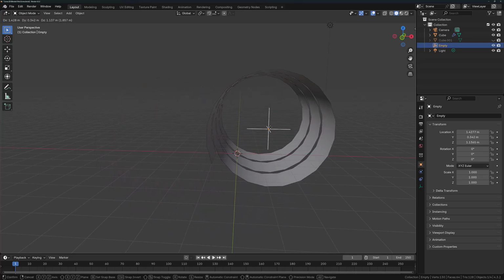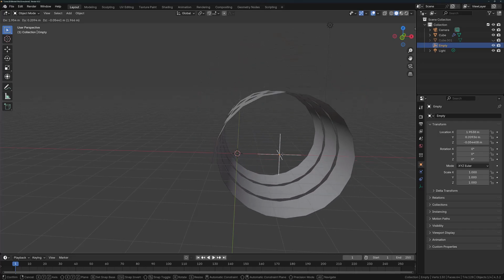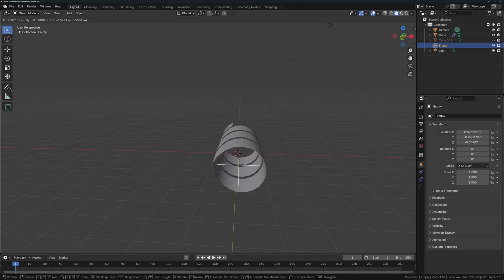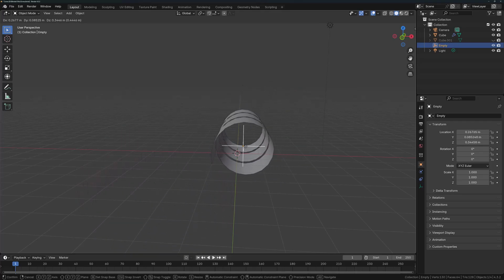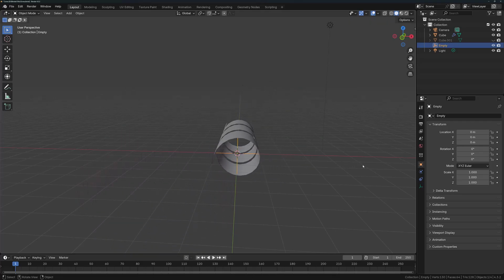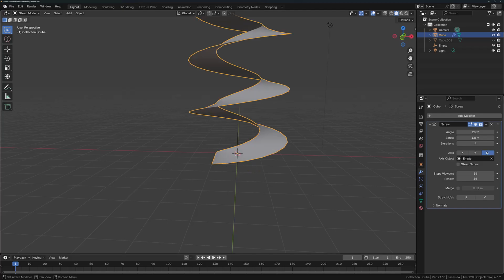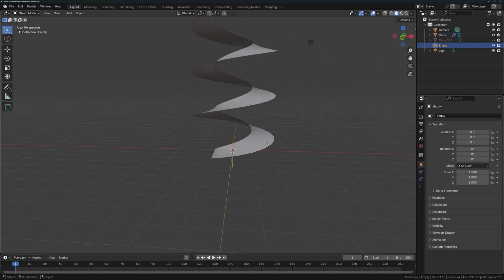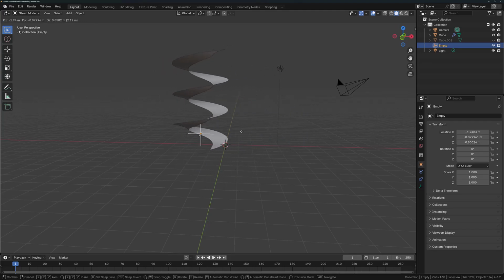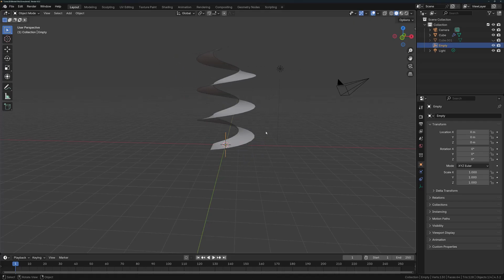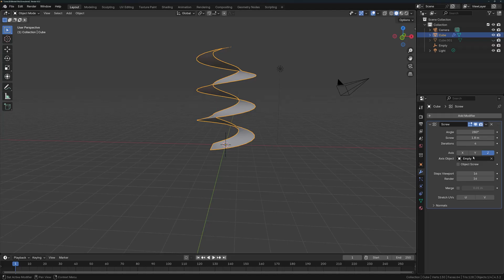And this actually does an even better job at manipulating not only the size, but also the direction of the screw modifier. And then if we select again, we can go to the Z axis, take our empty object, press G, and again we can manipulate the positioning of the empty, and this changes the behavior of the screw modifier depending on our selected axis.